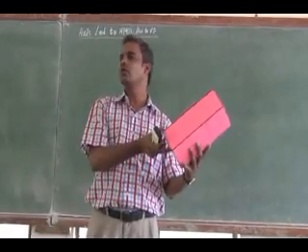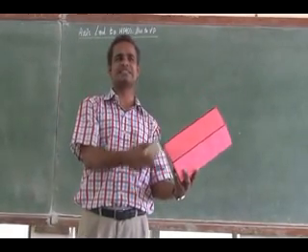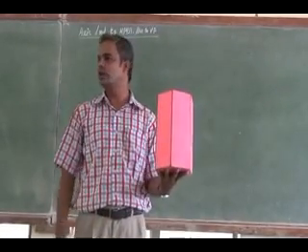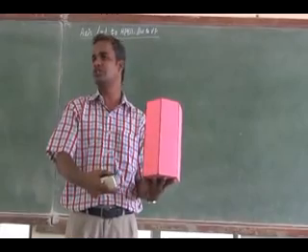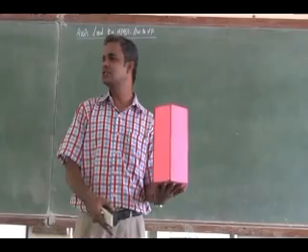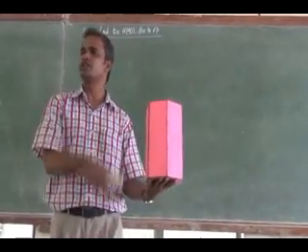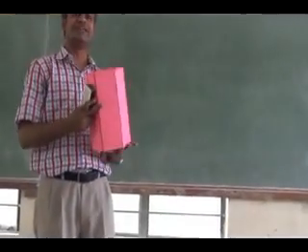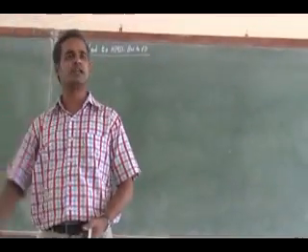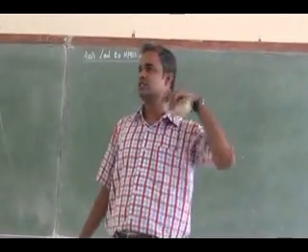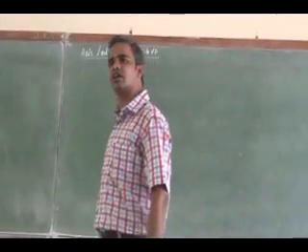So what we have to do? Wherever the axis is inclined, I have to make it perpendicular to that. So now the axis is perpendicular to HP. I can draw a simple two positions, front view and top view. Since the axis is perpendicular to HP, the base will be seen in the top view. So the top view I can draw, and the front view I can proceed. Then in the second step, the front view will be tilted to the given inclination. Then we will obtain the final top view, right?